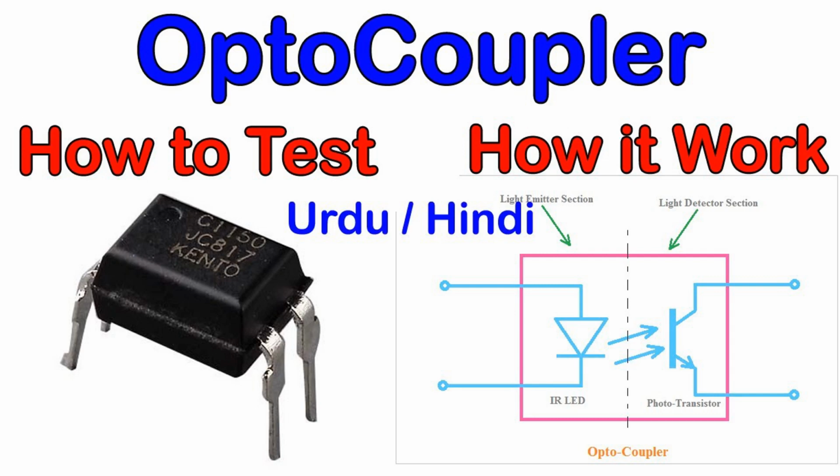Electrical safety. Galvanic isolation is often used to ensure the safety of users and equipment. In cases where high voltage or high current circuits need to be controlled or monitored by low voltage circuits, galvanic isolation prevents dangerous electrical currents from flowing into sensitive components or personnel. Noise and interference reduction: it helps to prevent electrical noise, electromagnetic interference (EMI), and radio frequency interference (RFI) from propagating between different parts of a system. This is critical in applications where signal integrity is important, such as data transmission and telecommunications.